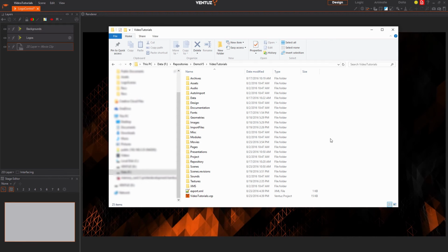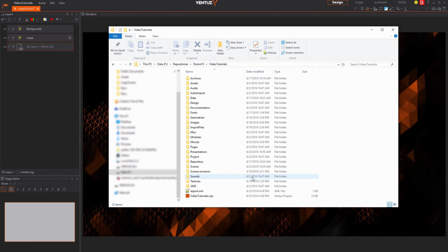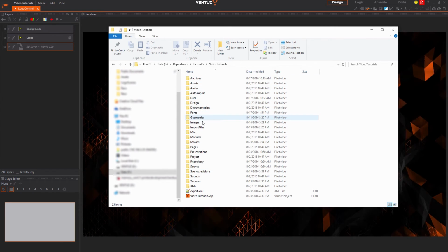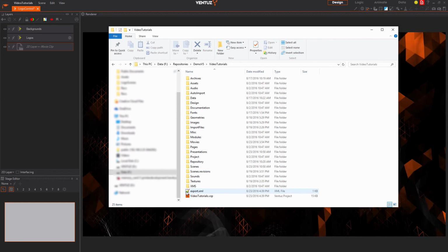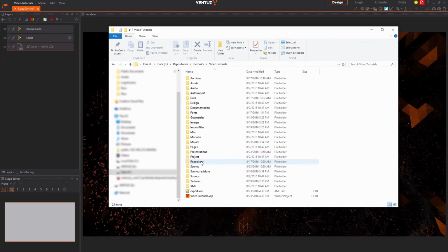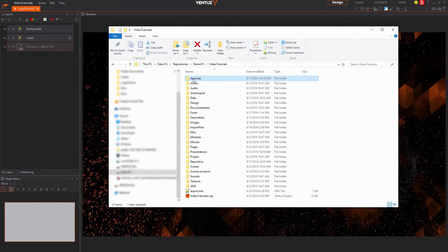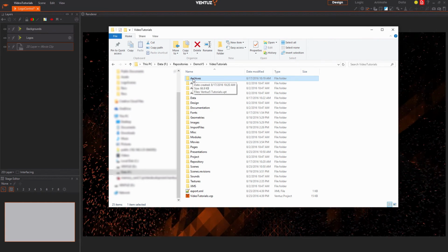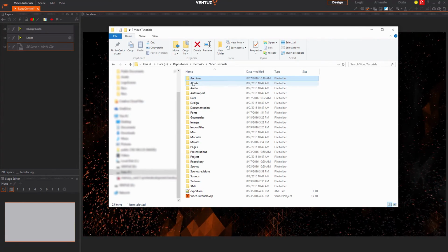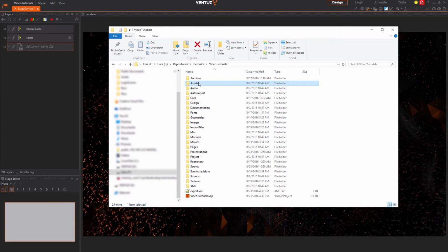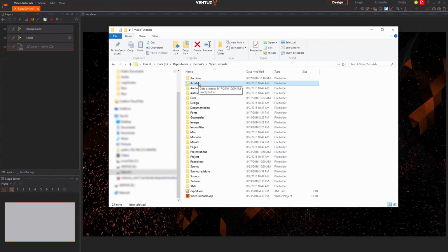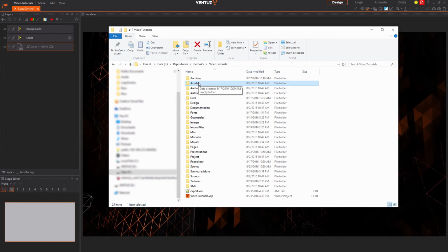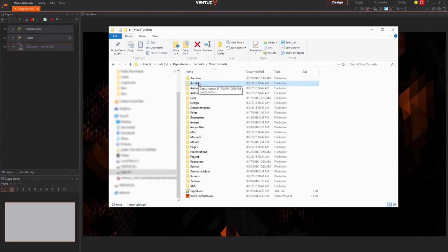Next, let us jump into the structure of the assets in the Ventuz project and the most important data pools. Each pool has its respective folder in your project's directory. Archives holds all compressed archives of either single scenes or the whole project that can then be imported on other machines with all the needed scenes and assets. Assets is used by the Ventuz Director and holds all images, movies, data files and the like that you want to use during the running director-controlled show, but not in your design process.